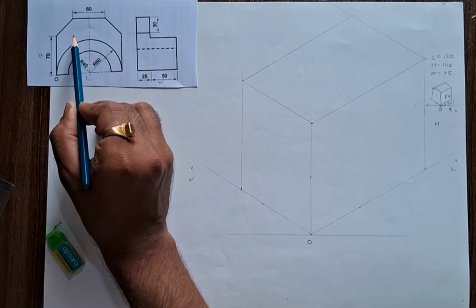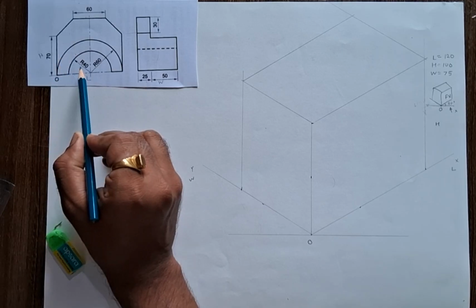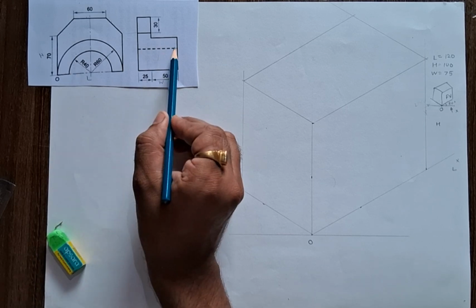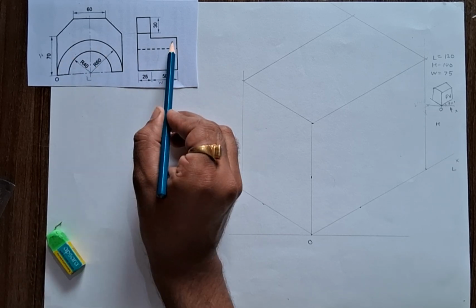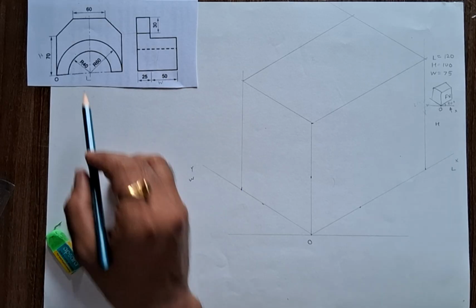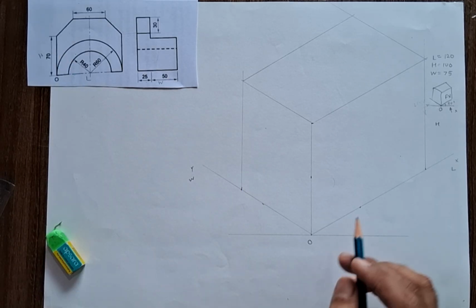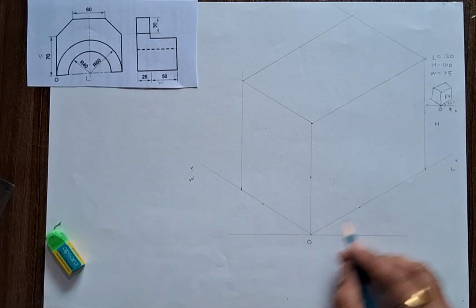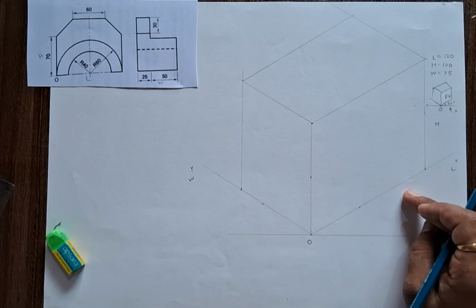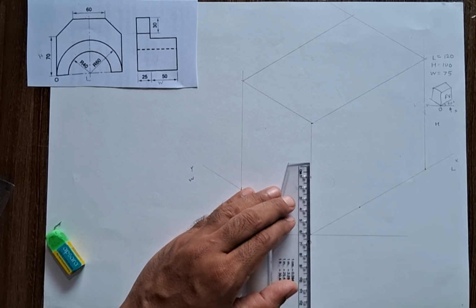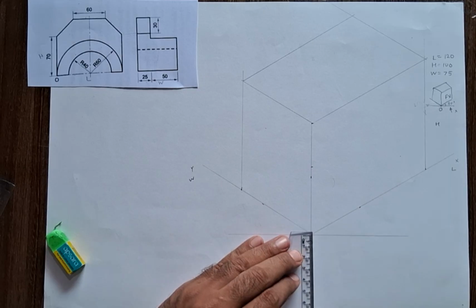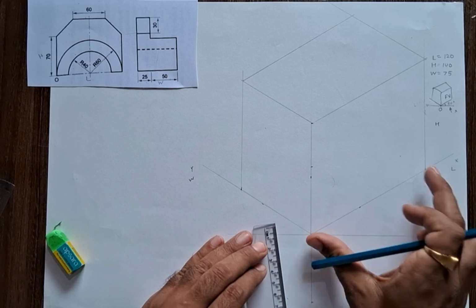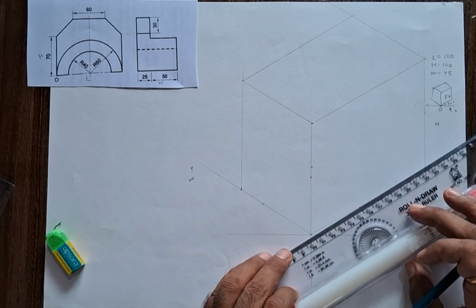So this object consists of two parts. The half circular part is hollow. This 40 mm radius or 80 mm diameter circle is throughout, and the upper half circle's thickness is up to 50 mm. So we can draw an outer half circle and inner half circle. For that we require a rhombus of dimension 120 by 120. Here already this length distance is 120. So above this length on the x-axis mark 60 mm, and below this O point mark 60 mm. So a 120 by 120 rhombus is required for the outer circle.